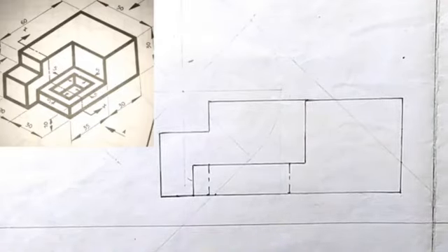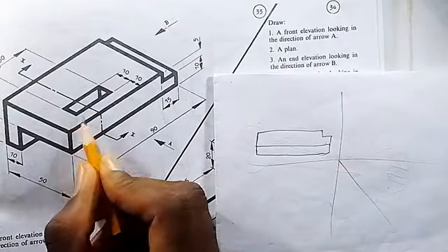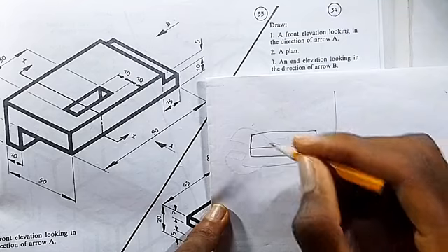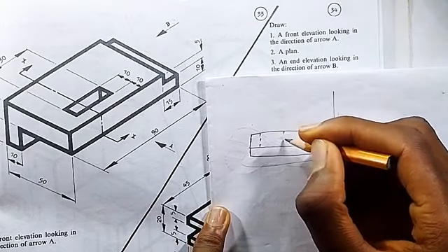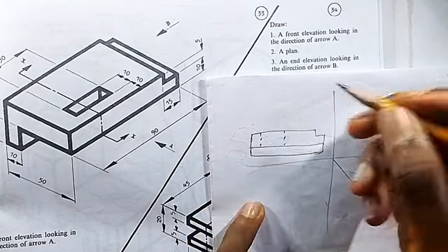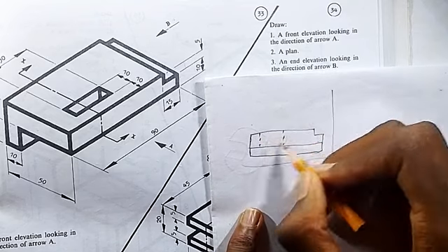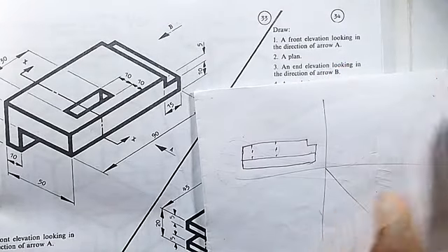So at this point where the hole is, we just draw a hidden detail. Remember, the hole is only at this top part, it does not reflect this part here. So at this top, we draw a hidden detail, a cutting line, to signify that there is a hole at that part. So someone will understand that yes, there is a hole at this end here. Good. The front elevation has come to a completion.